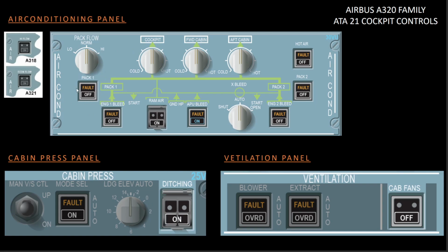And there's another thing, so we call this the pneumatic closure. In case all other parameters are okay, if the upstream pressure at the flow control valve itself is less than the specific value, the flow control valve will remain closed.